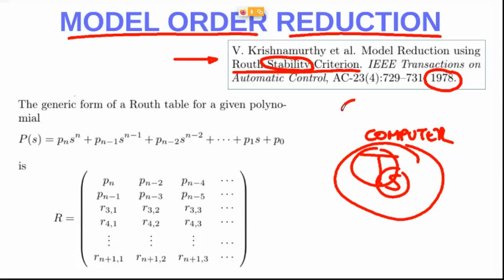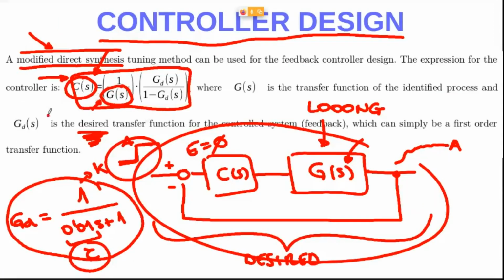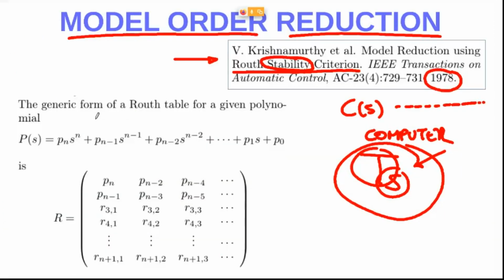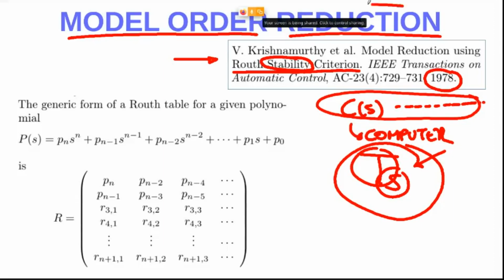So that's why a controller C(s) that is so long will be so difficult to operate with these polynomials in a short sample time. That's the idea. This is a practical issue, okay? On the blackboard, everything works. If you apply this formula in here on a blackboard, everything works, okay? You can get C(s) if you have G and Gd, okay? It's easy. But the problem starts when you have to code this on a real problem. The aircraft is expected to fly, so you cannot bring a controller so long to this computer, okay? That's the idea. So that's the need for our model reduction.